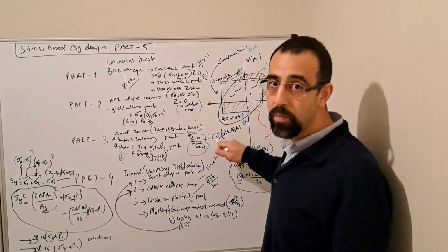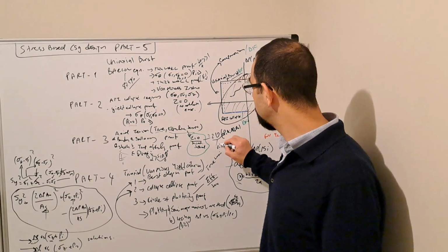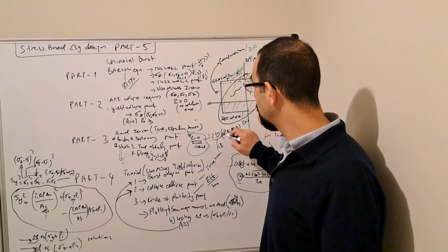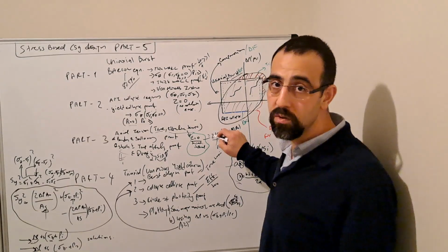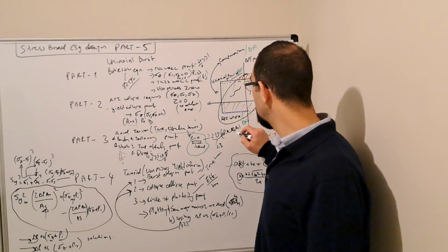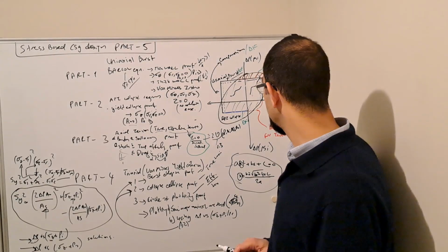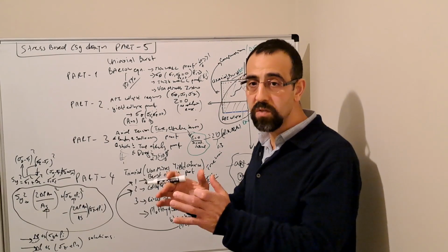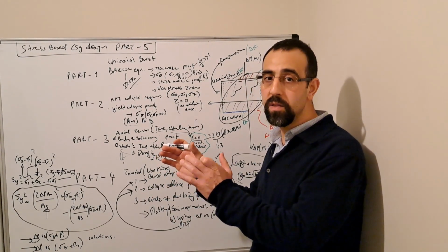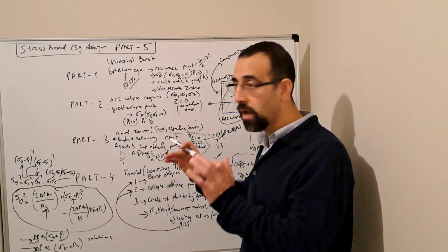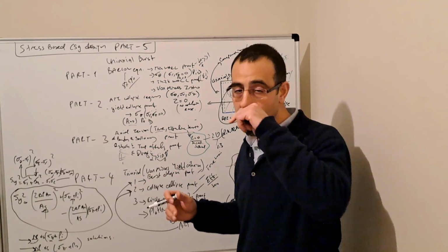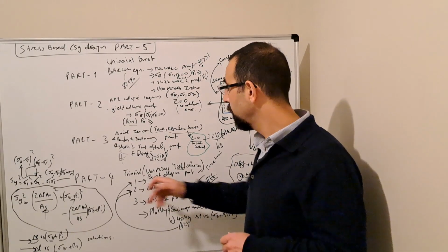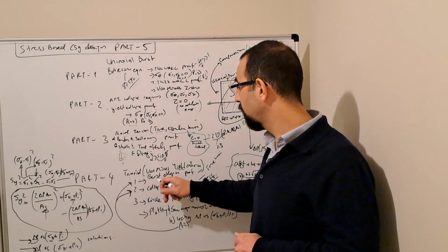force is equal to 2 times the Poisson ratio, which is 0.3 for steel, times the delta difference in the multiplication of the internal pressure times the inner area minus the delta of the external pressure times the outer area. So what we said is there are the initial conditions where it's cemented, and then there's the life of the casing, where all these effects are put in, and then you sum everything up to come up with a final tension profile.